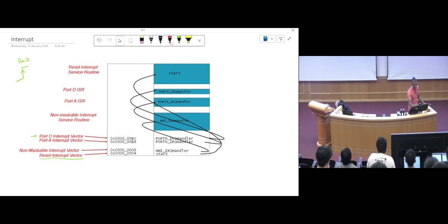Initially it was in the main loop, doing something, correct? And now the push button has come in, the interrupt has been triggered. So what do I need to do? I need to first do the hardwired activity, which is saving the context. So from here I will first save the context when the event happens. Now after I save the context, I need to jump to the ISR, correct?